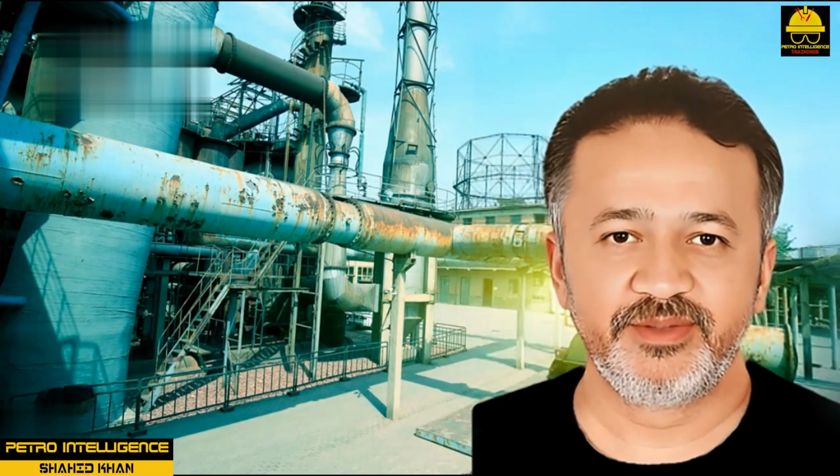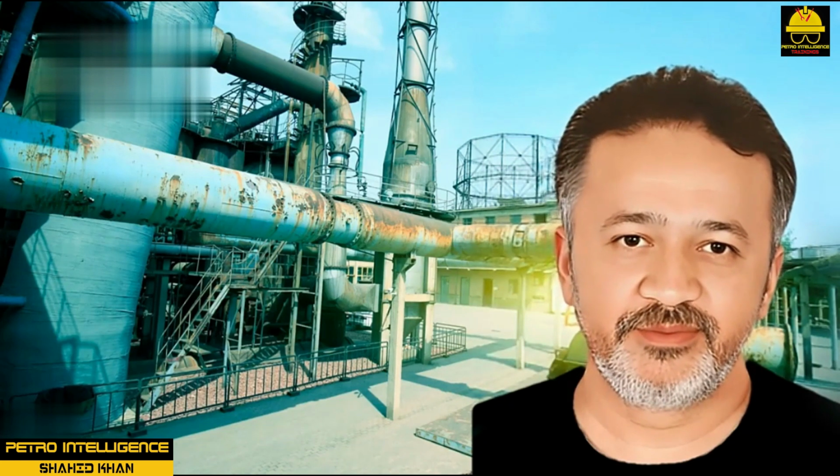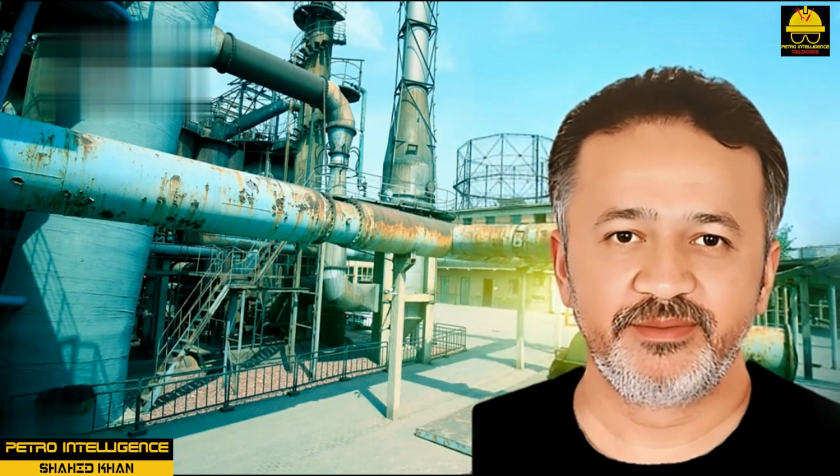The various branches throughout the unit terminate in a stainless steel header sloped to drain to the cold flare knockout drum. The cold flare knockout drum is a stainless steel drum containing a heat exchanger that vaporizes the accumulating liquids. The vapor exiting the knockout drum is kept above 32 degrees Fahrenheit or 0 degrees Celsius.